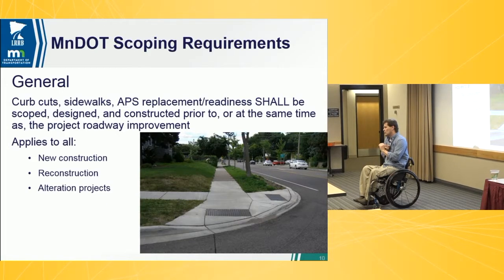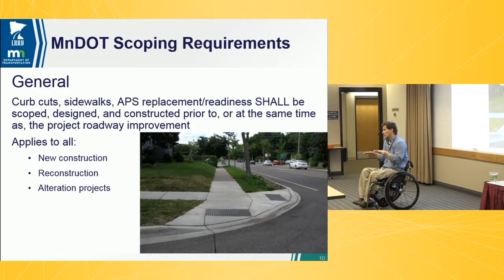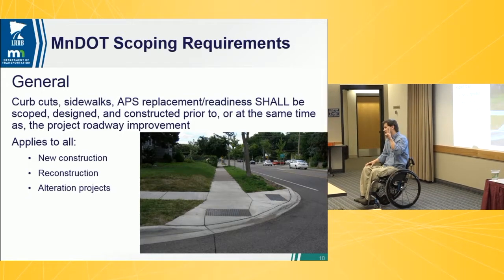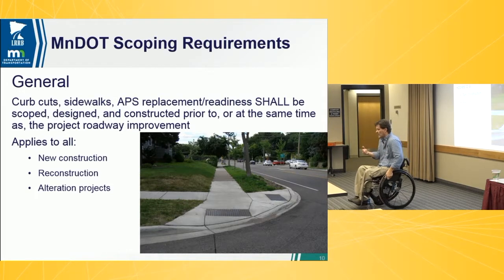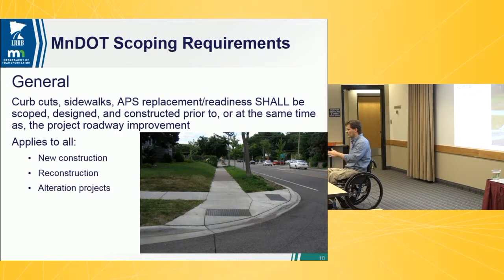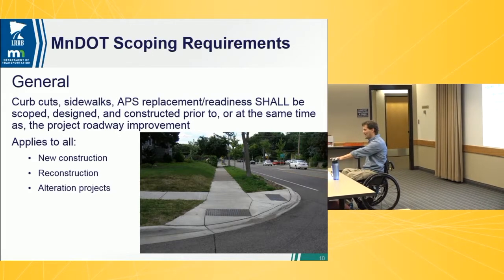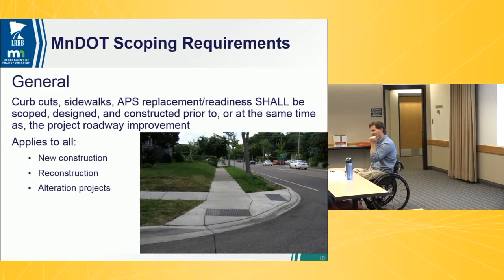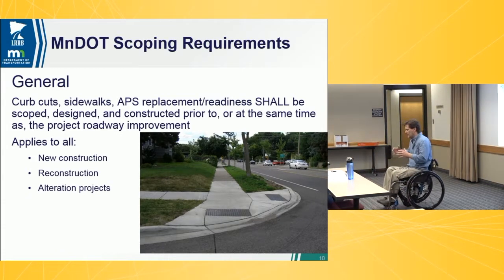The other trigger is the cross slope, and we're saying actually 3% is our threshold. We know everything we build has to be less than 2%, but we're not going to go out and fix absolutely everything because we are financially constrained as well, and we want to get the worst first. But also it's hard to explain to a citizen why they have this really good shape 2.5% cross slope sidewalk, and you're ripping that out and putting it back very similar. So we're doing that targeted type approach, not fixing everything, but again, getting the worst.